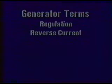The second is reverse current. The generator must always be a current supplying device, never a current consuming device. Remember, we can motorize a generator by supplying electric current to it, rather than extracting current. Under certain conditions, such as during engine shutdown, when the generator rotation begins to slow down and the output slowly decays, the generator could act as a load on the electrical system and begin consuming electricity. Should this occur, damage to the generator or the aircraft wiring could occur.